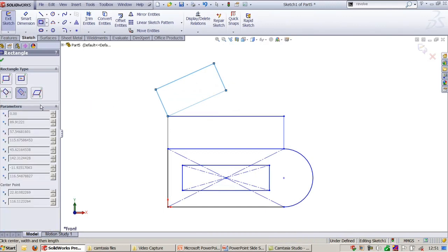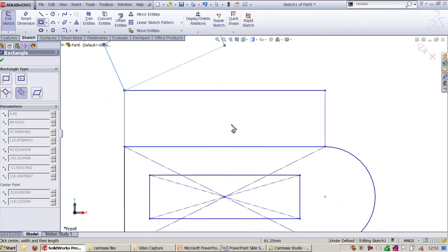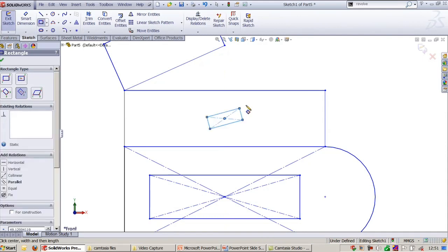And once again, there is one more challenge. I need to create a rectangle where it should be exactly centered, but it should be oriented. Now I'll select a point from here. I'll take this point as the first point, and select the second point from here. Now you can see we'll get the midpoint using this tracking, and I'll select how much angle you need, and I can choose a rectangle here. I can create this rectangle.